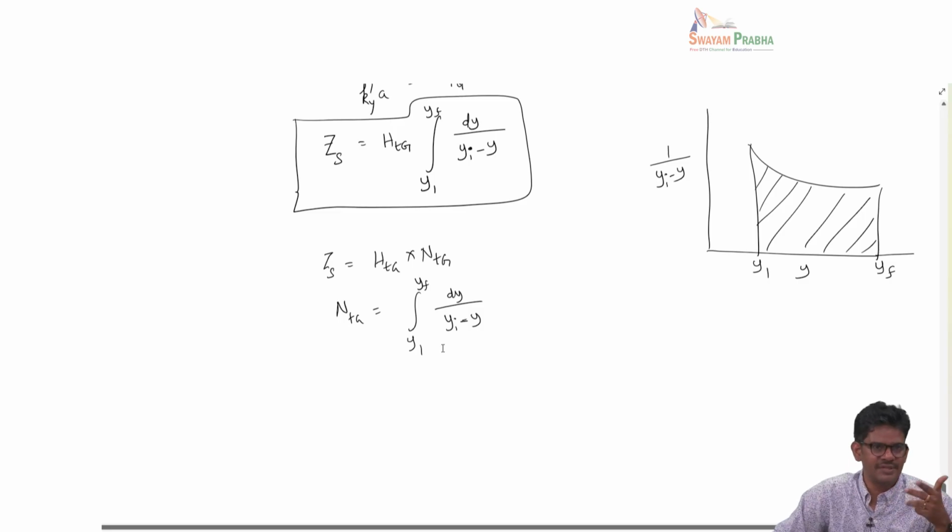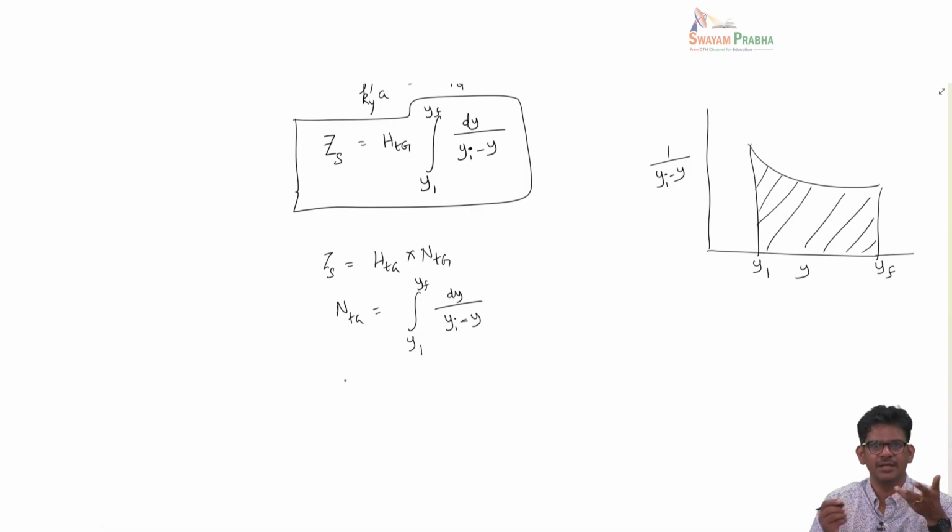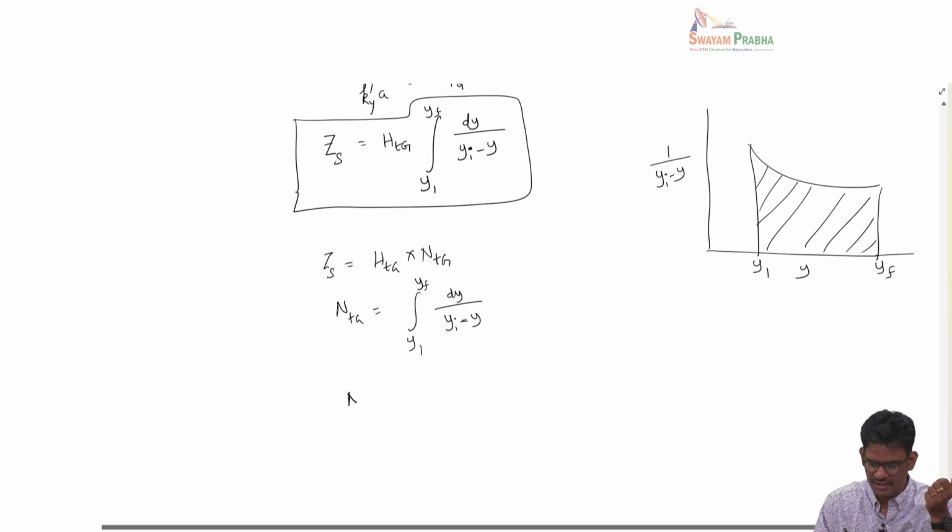Some of the problems I solved in the class, I think batch distillation, had a similar kind of integral, and we approximated the equilibrium line to a straight line for a very narrow range of concentrations. Suppose you do continuous vacuum distillation; in those ranges we can approximate the equilibrium line as a straight line. So in those cases, it makes sense to define the overall NTOG.